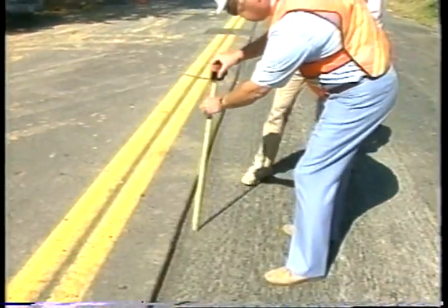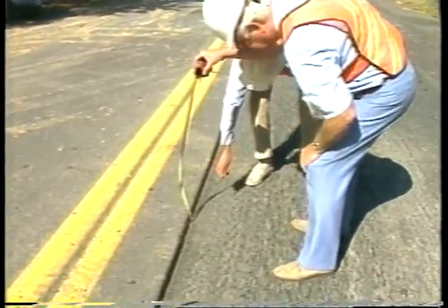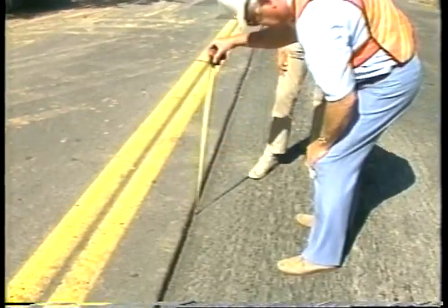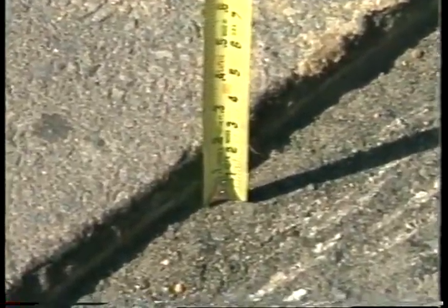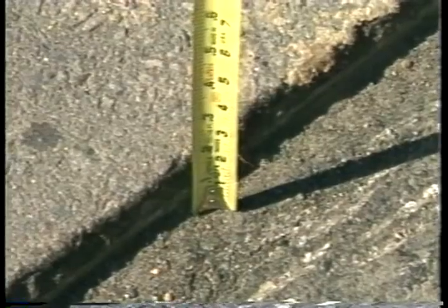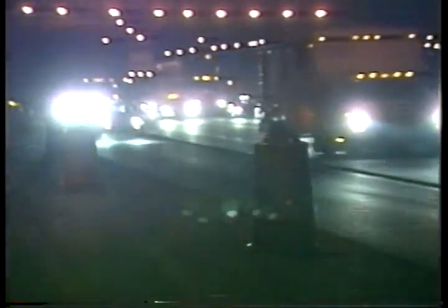They should pay special attention to pavement shoulder drop-off policies. Any drop-off is considered hazardous, but those greater than 5 centimeters left overnight and immediately adjacent to traffic have a high accident potential.